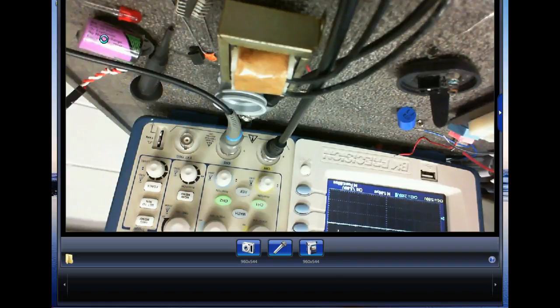We're going to have more series paths, and we're going to have to heat sink them. But they're real easy to design. These switching supplies right here are not easy to design, no matter what he said, and they're basically real hard to troubleshoot, because you have to start that oscillator up, so there's a feedback circuit in there. But what you'll find is that usually you can't fix these because they're sealed. If you take this thing apart, it's all sealed up.